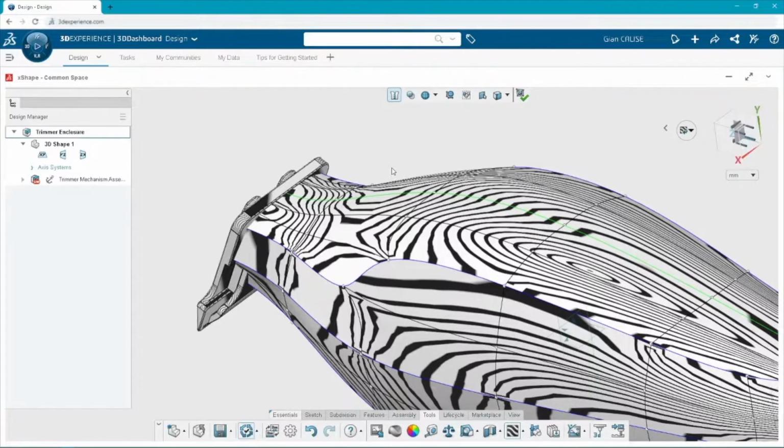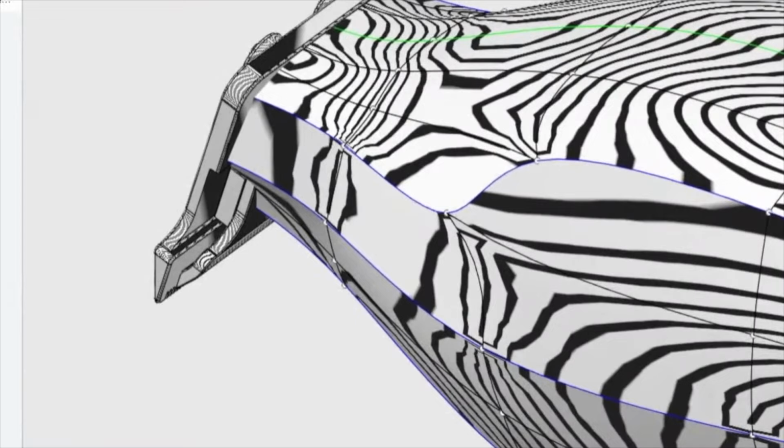Yeah, sure. I'm going to zoom in a little bit. So when these zebra stripes get very flat or you just get large spaces in between them, like for instance, right in the center of the screen right now where it's very white, that just means that surface is getting very close to planar. And the more crazy and kind of wacky the surface starts to look, the more the stripes start to all come together at a certain point. That's how you know that you might have kind of a puckering surface there, or you just have a very dramatic change in that surface at that point, which may or may not be what you're looking for.